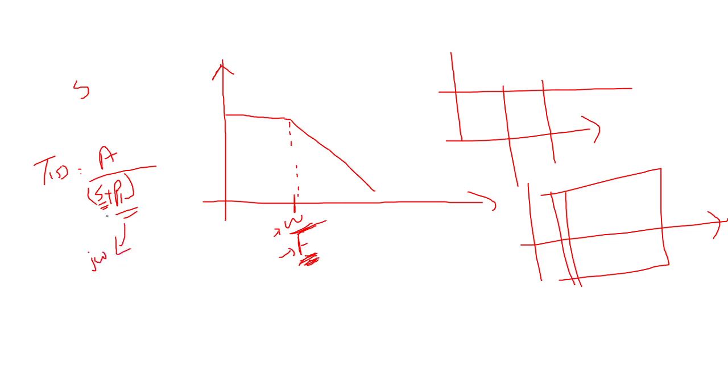That is the pole, so that must be in omega terms only. While plotting the Bode plot, if we got omega, we can map it into frequency f, that's fine. But we cannot say the pole is in f. It will definitely be in terms of s. S equal to minus p1 is the pole. What is s? It is sigma plus j omega. So there we have to consider omega only, not f. We cannot write jf or f.